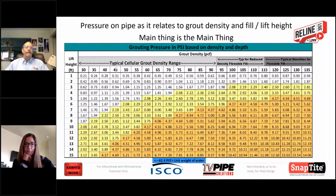And we can see here with a 40-pound grout, I can go down 7 feet deep before I ever have to really worry about getting to my limit at a 2-to-1 safety factor. And I can go down 14 or 15 feet deep before I'm really ever concerned that I'm reaching the limits of that liner pipe. Now, if I get over here in 100, 120 pounds per cubic foot, when I go 2 feet, I've reached 2 psi. I'm at my safety factor. And if I go to 4 or 5 feet, I'm now at a risk of buckling the pipe.